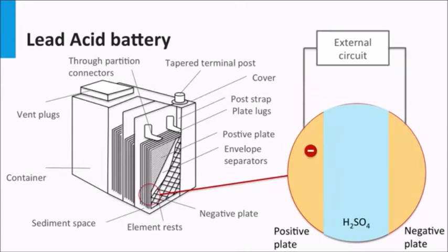When the battery is recharged, the flow of electrons is reversed, as the external circuit doesn't have a load, but a source that has a higher voltage than the battery to enable the reverse reactions. In PV systems, this source is nothing but the PV module or array providing clean solar power.